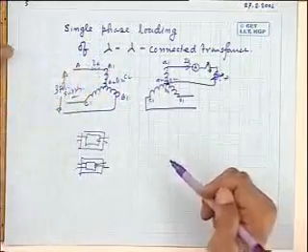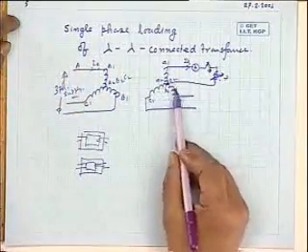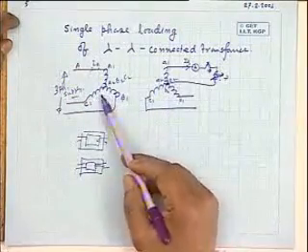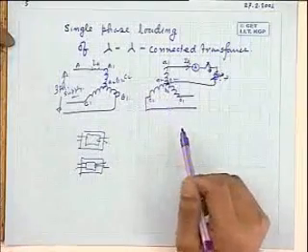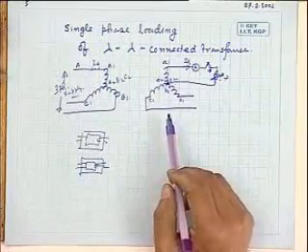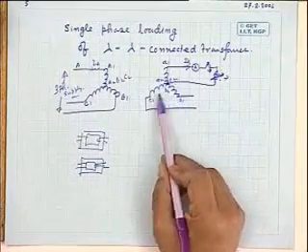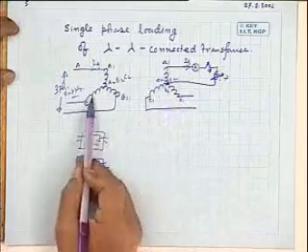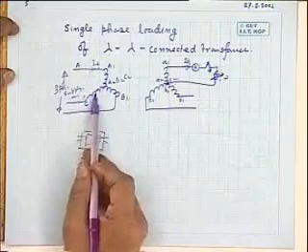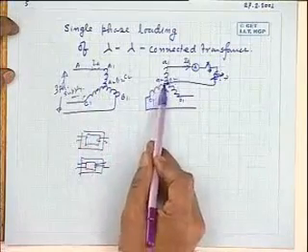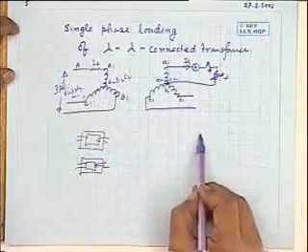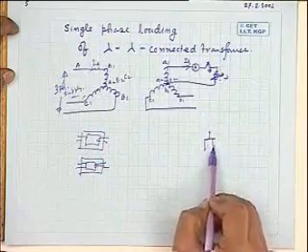But if it flows through the B and C lines, the secondary of which is not carrying any current, then the flux in these 2 transformers will be upset, is it not? So what I find is that on the secondary side, B phase and C phase are not loaded. What impedance will it see? Only the magnetizing impedance of this winding and of this winding, because here nothing is connected.